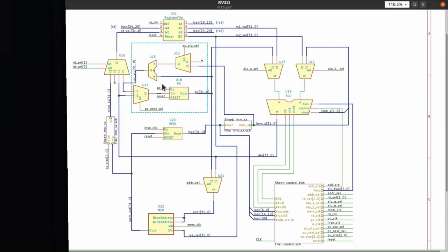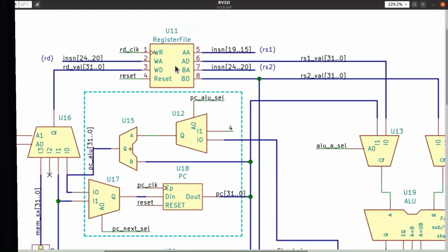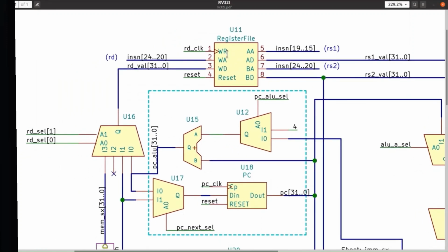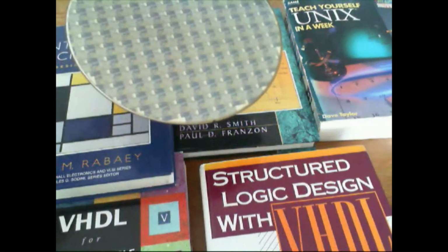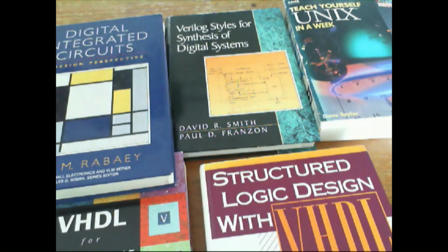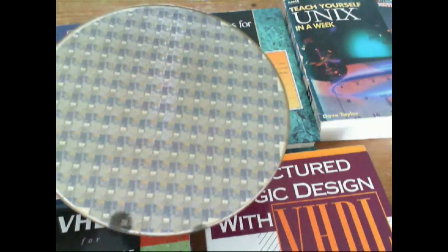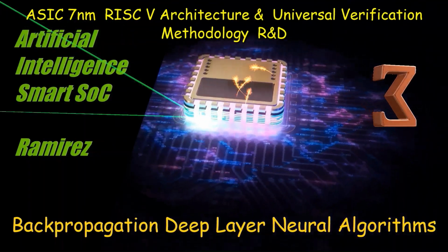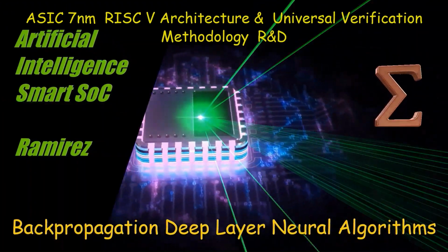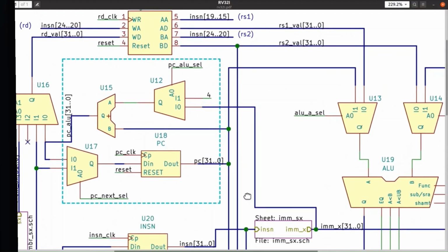So continuing with the scan controller, then cd verilog/dv/scan_controller. Next line would be make test_scan_controller. At the gate level, simulation requires scan_controller and user_project_wrapper to be rehardened to get the correct gate level netlists.